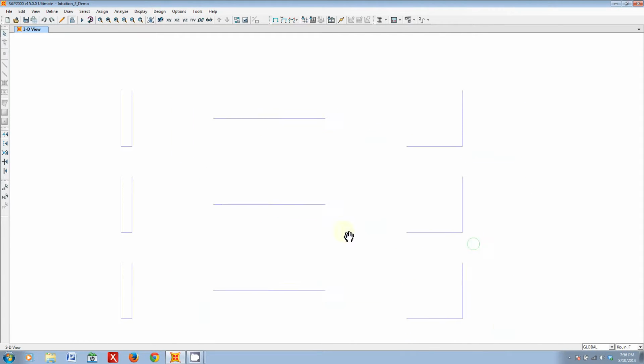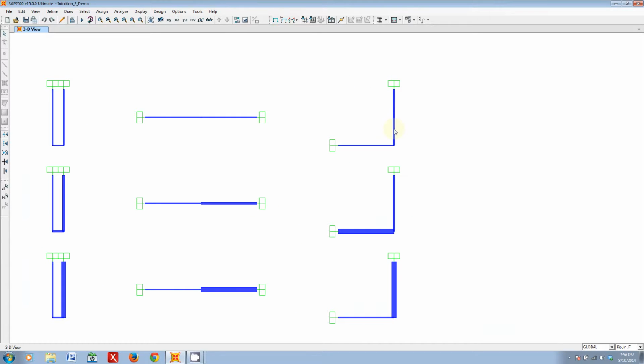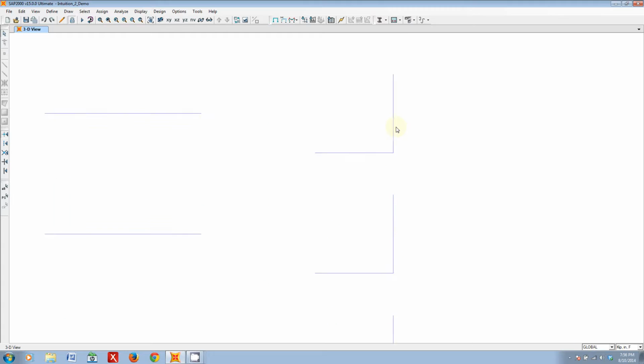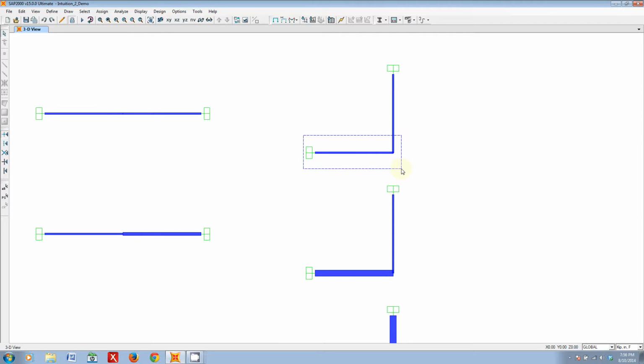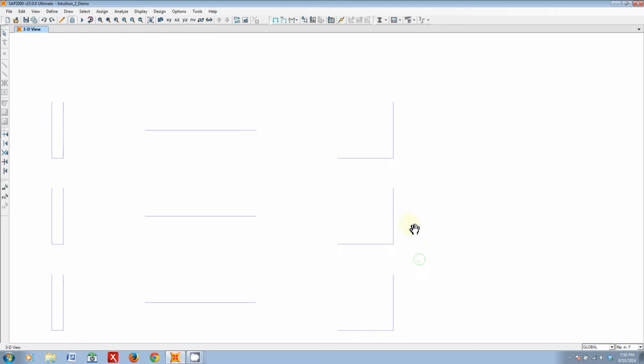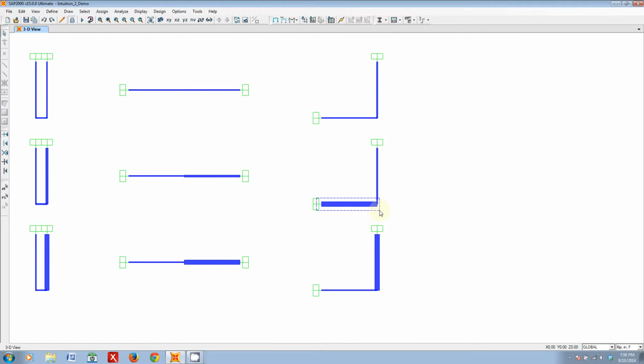Hopefully. Now the last case is a combo between an axial rod connected to the ceiling, and then our nice little beam coming in here. Now, I'm sorry to say beams aren't very good stiff members. It's just kind of a pity. These rods just kind of win out every day. You'll see that mostly the rod is going to carry most of the load. Even in the case of a really thick beam, it's still not going to carry that much, just because beams are pretty flimsy. It's the rods you want.